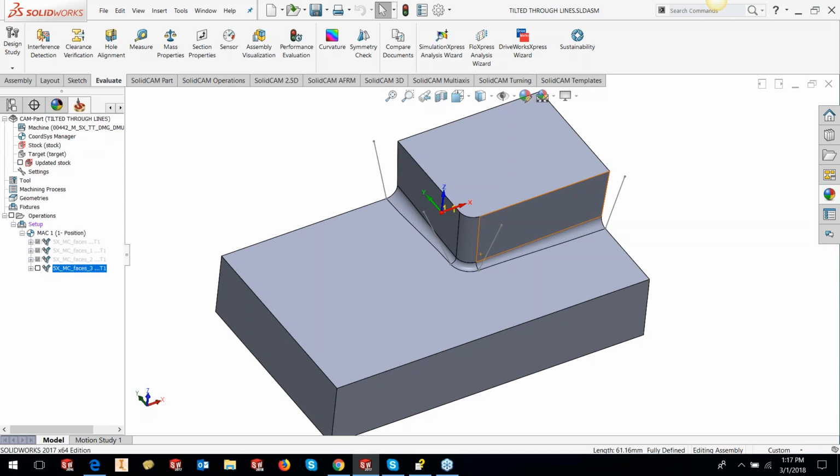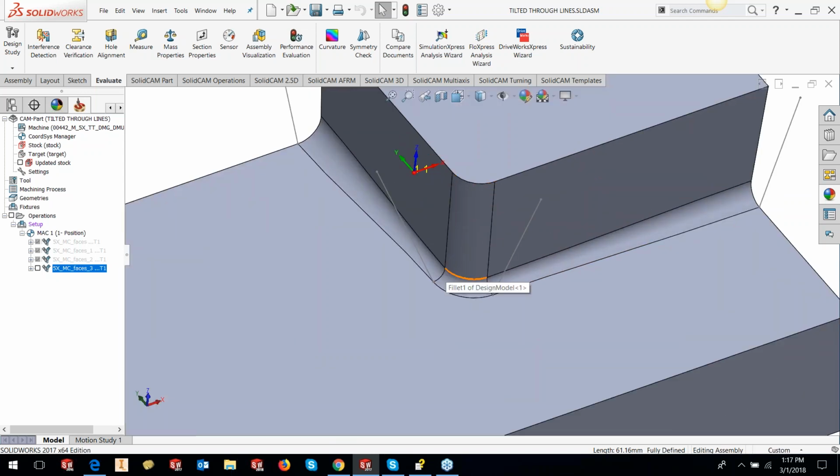Sometimes we just give 0.5 and it doesn't do anything. Then we change it to 1 millimeter. Also, it doesn't do anything. So in that time, you need to measure from the furthermost point on the surface to the line. What is the distance that you're getting? And that distance is what you're going to use as your snap distance value. Okay.